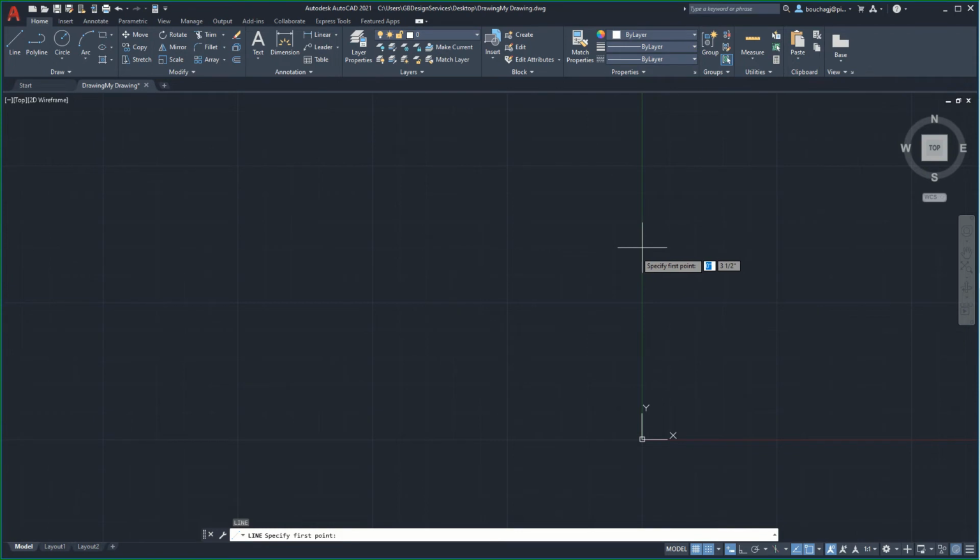I have found that the floating dynamic input boxes sometimes cover or interfere with objects I am wishing to work with, and also find them to be generally distracting. Some users really like this tool. I leave this tool disabled. This is an example of how each user has options in managing their work environment. The F12 key will toggle this tool on and off.